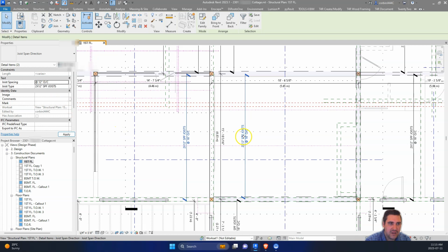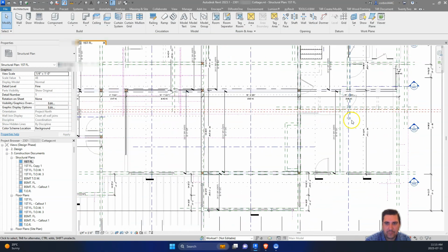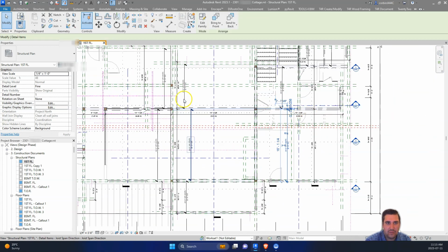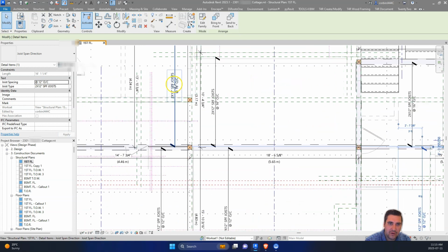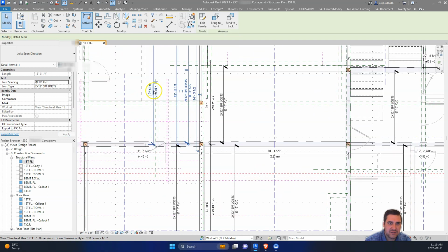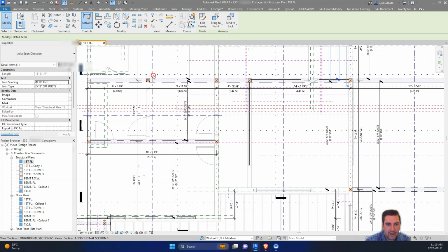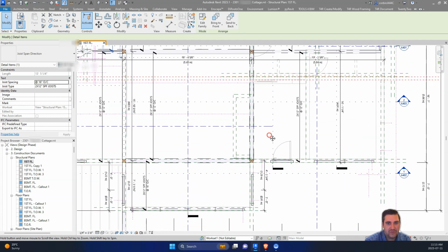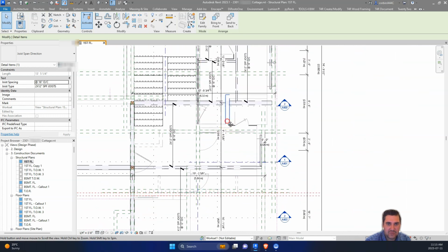This one over here would have to be 12-inch centers as well. And then over here, this could be 16s because it's under that 15'5". Let's just see if we have any other locations that are under that. And we'd ultimately want to keep our joist sizes the same. So 2x12s here, 2x12s. Yeah, so we keep the same joist size across the whole project, even though, for example, this span's a lot smaller, we would still keep the joist size the same.